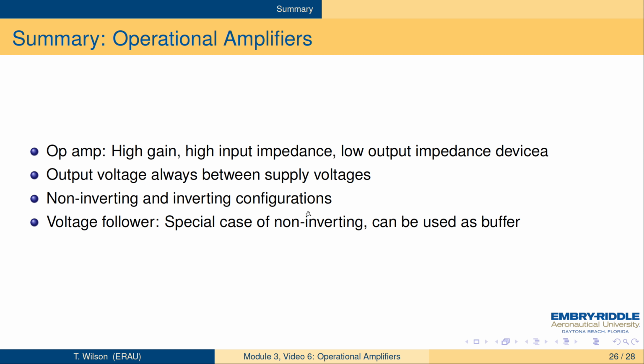So where do we go from here with these? We're going to be able to design arbitrary low order, first, second, third order circuits, because now we can design with real poles and even with complex poles, we'll see, because now we can hook up a first order circuit to another first order circuit to another first order circuit. And so we can certainly cascade first order circuits to generate sets of real poles on the negative real axis. So design is what's next. We've got the tools we need from what we've done previously and now with op amps.